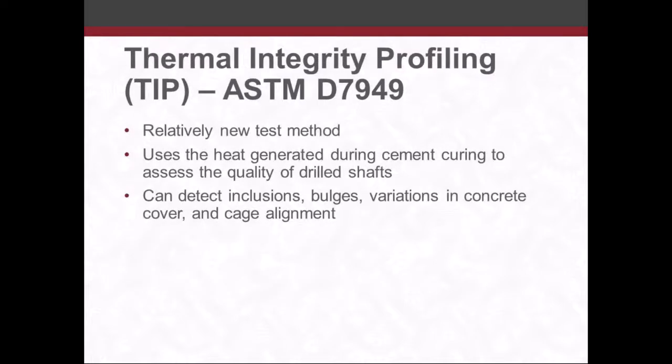The thermal integrity profile. This is a relatively new test method. We did just see it in a spec somewhere here. I can't remember if it was in New York State or not, but basically it uses heat generated from the curing process to assess the quality of drilled shafts.